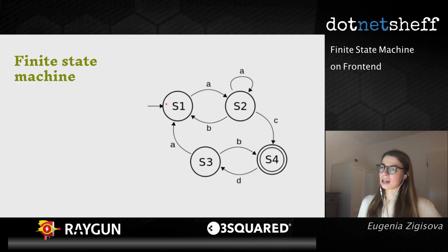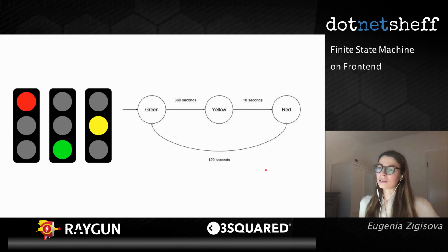This machine has an initial state and also a final state. One of the simplest examples from the real world is a traffic light. There are 3 states in total: green, yellow, red, and the transition between them happens in response to timer events. And it would be a pretty bad situation if this state machine could have 2 states at a time, like red and green simultaneously.